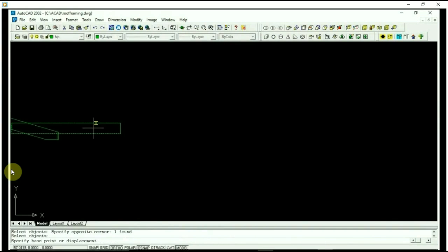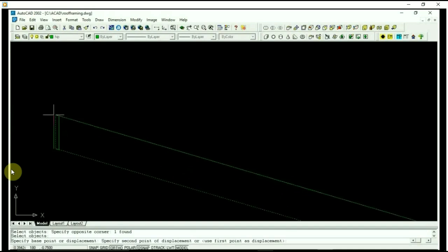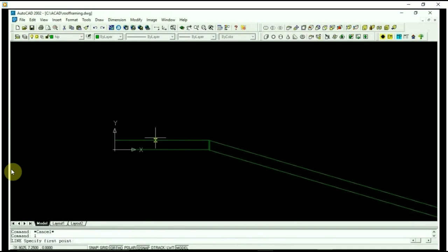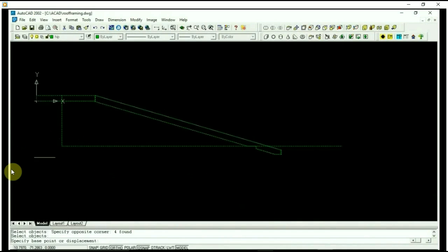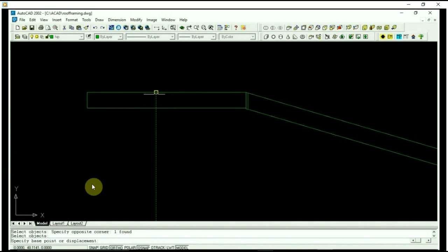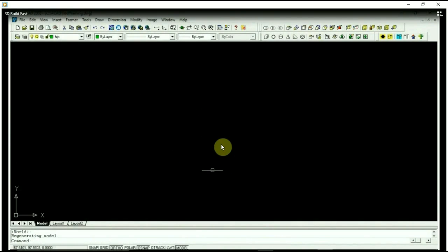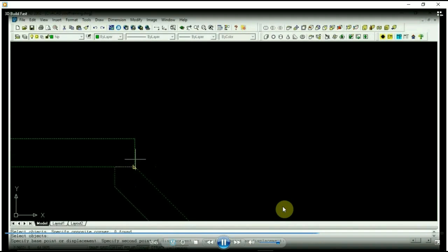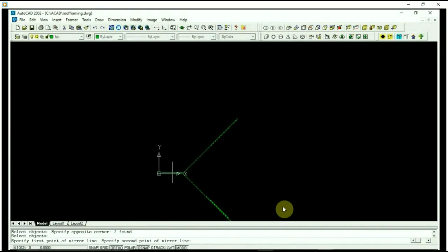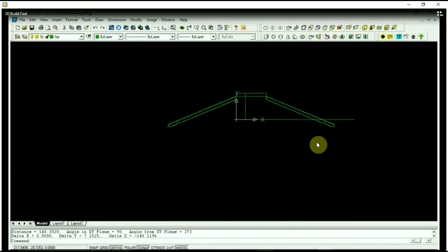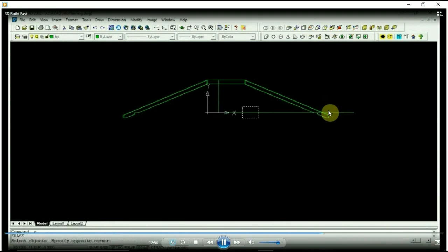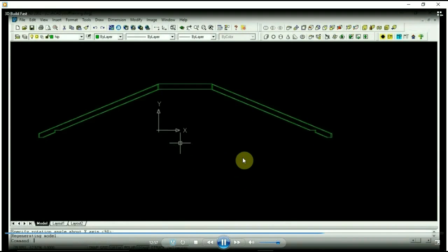And right now what this is doing is making the roof. I'll move on and talk about this real quick. What I'm doing is setting the hips, and this is important with roofs since I'm working in different planes here. My common work point for my rafters and my ridges is this seat cut down here at the bottom. I put the ridge in first, then drew a vertical line down the distance to the top of the wall, and then a horizontal line across to set it. That's what I'm doing right here, resetting all the hips back. That horizontal line represented the top of the wall. So now the hips are in.